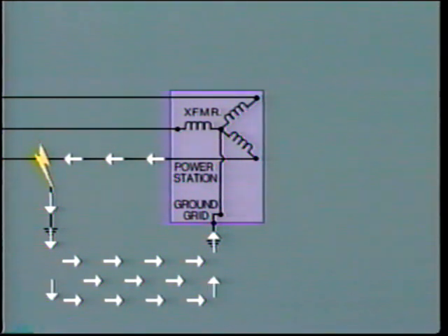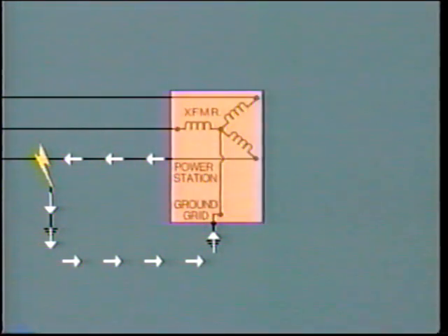Actually, the current flows through the earth in many parallel paths, seeking the least resistance, usually deep down, not on the surface. Consequently, the circulating fault current enters the grounding mat from below and from all surrounding directions. The current then flows through the grounding mat and returns to the transformer via the grounded neutral.